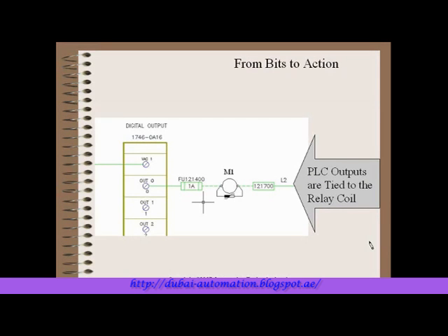Likewise, on the other side, we have our PLC outputs, which is a different type of card that interfaces directly to our relay, motor contactor M1. You see it has a surge suppression device around it to protect the PLC output. Also a fuse, which protects the output. But generally, the main thing is that you have this output directly from the PLC that goes to a relay coil to be able to operate some kind of real-world device.